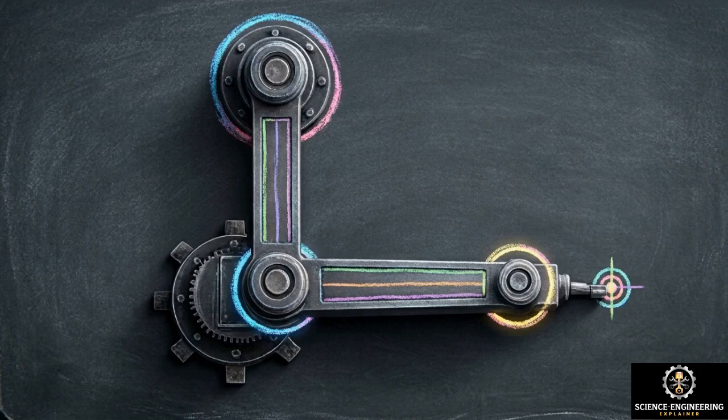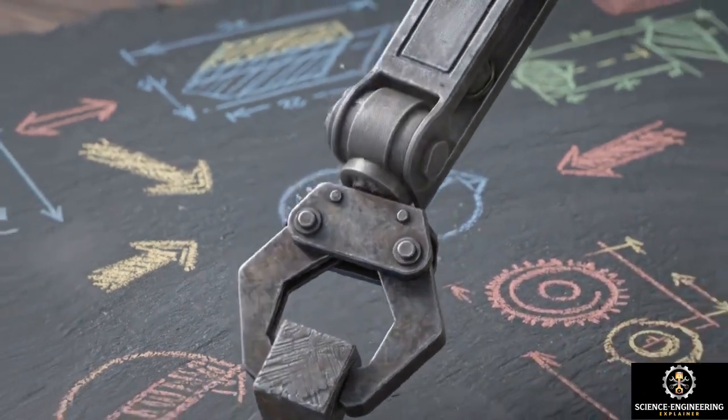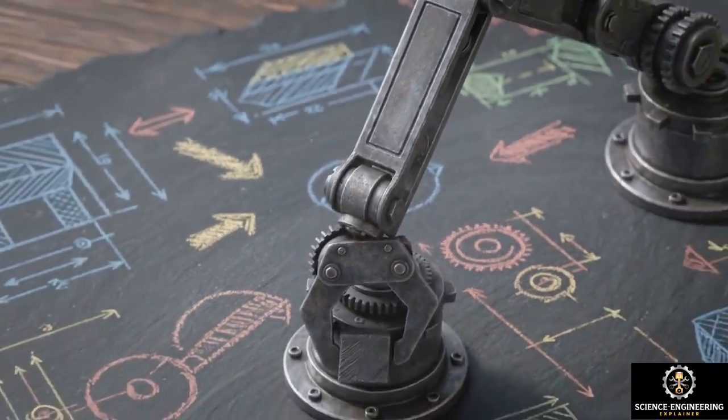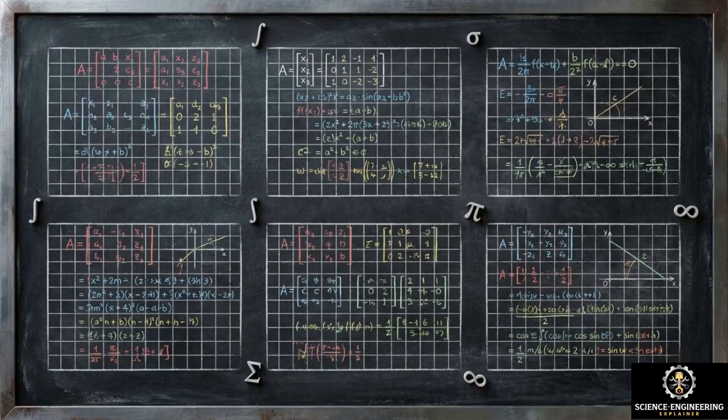If we knew the angles of the 3 motors and wanted to calculate where the gripper ended up, we would use forward kinematics. Inverse kinematics poses the exact opposite problem. Knowing the final pose we want, we must calculate the specific joint angles required to reach it. Systematic control of these joints requires us to reverse the forward kinematics model through a rigorous 6-step analytical derivation.